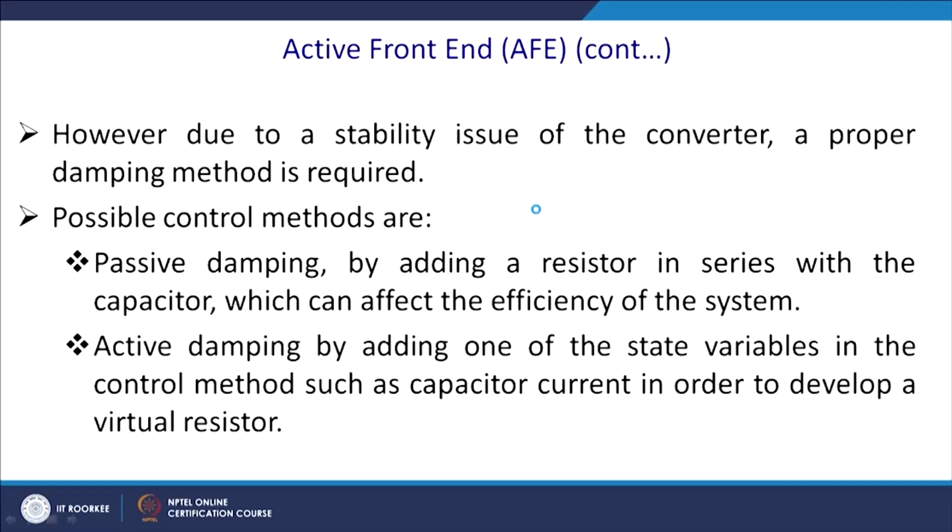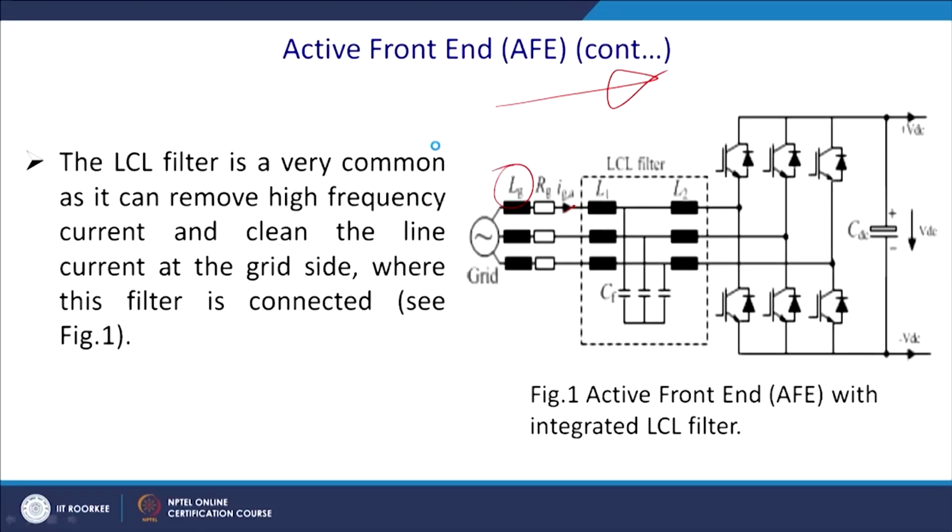However, due to the stability issue of the converter, proper damping is also required. Generally an LCL filter will give you oscillations, and thus these oscillations are required to be damped out. It becomes phenomenal when every switching is a transient. It is because its state will be changing.